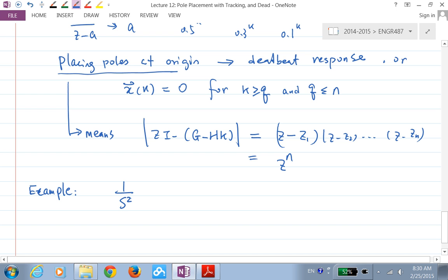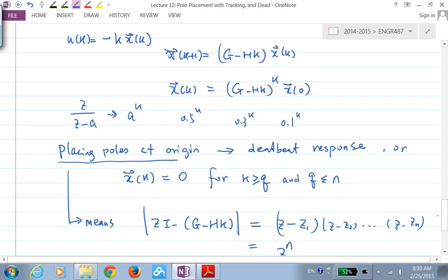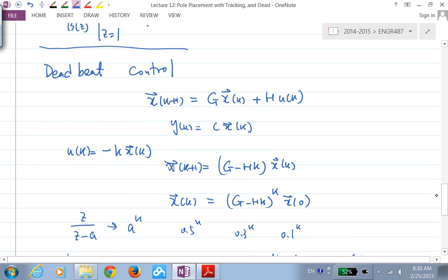You can also design the deadbeat for the reference tracking problem. Same thing. Because everything that we're talking about here is just selecting the K, right? If I modify this a little bit, just like the reference tracking, put it as K0 and R of k, like this. The same idea.